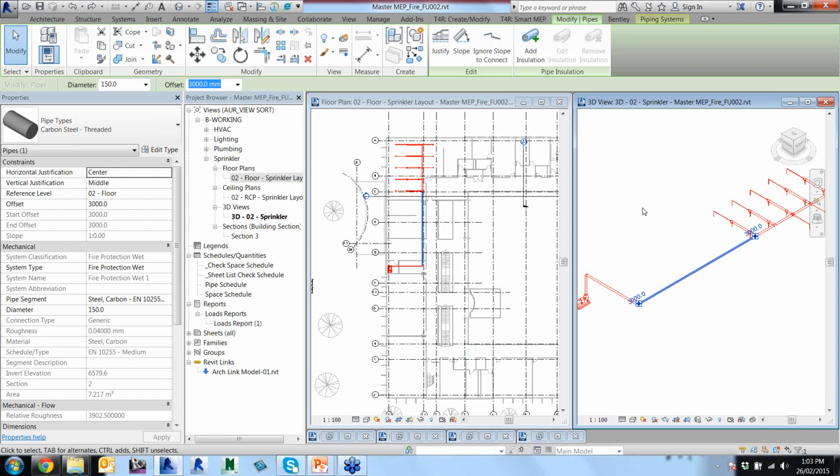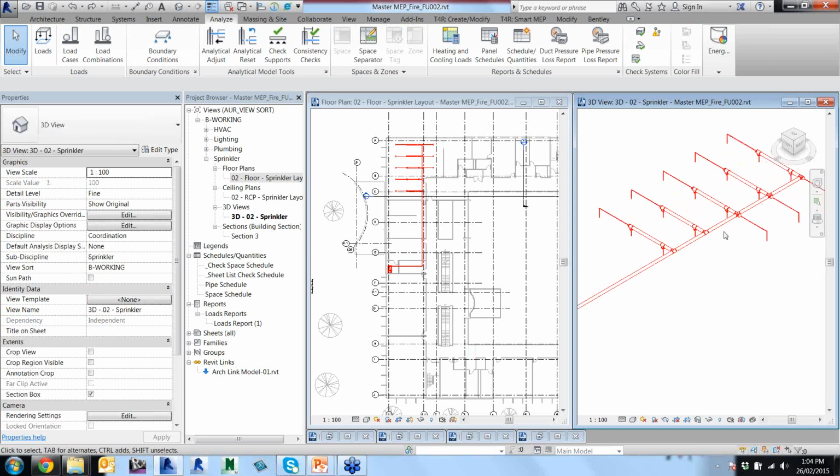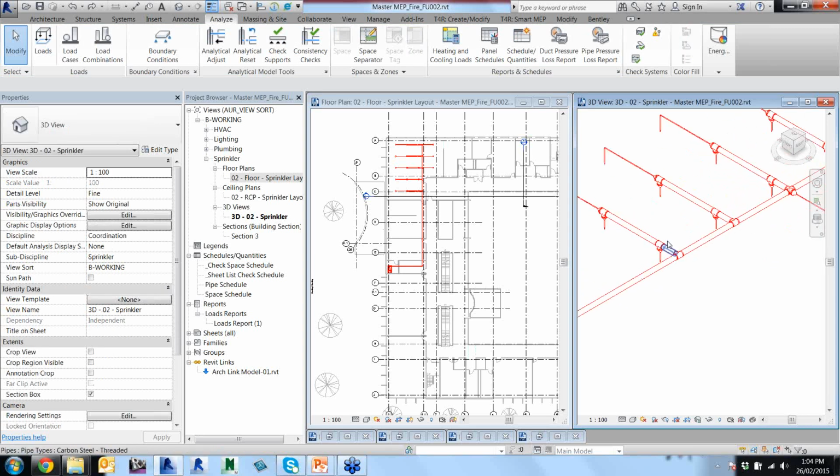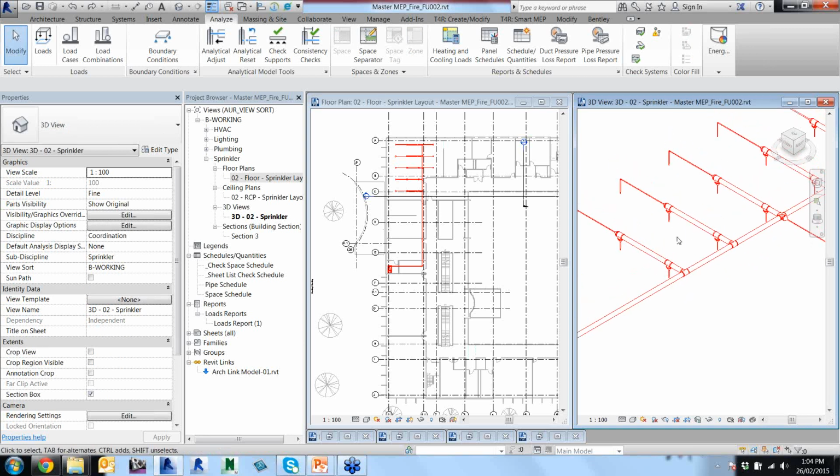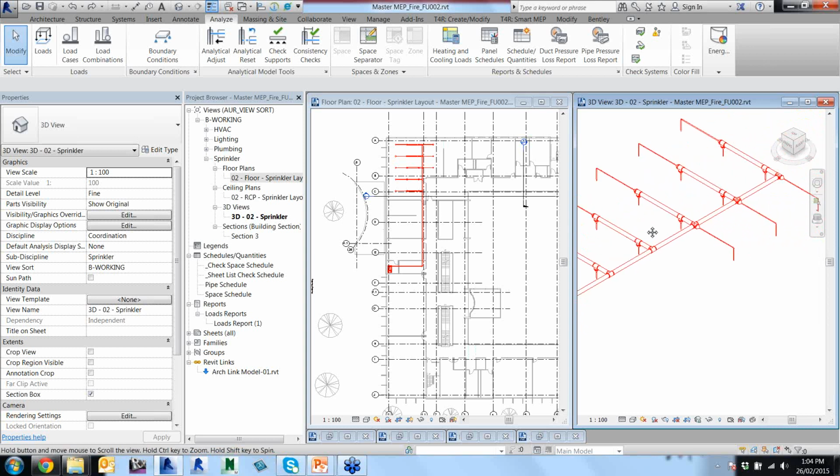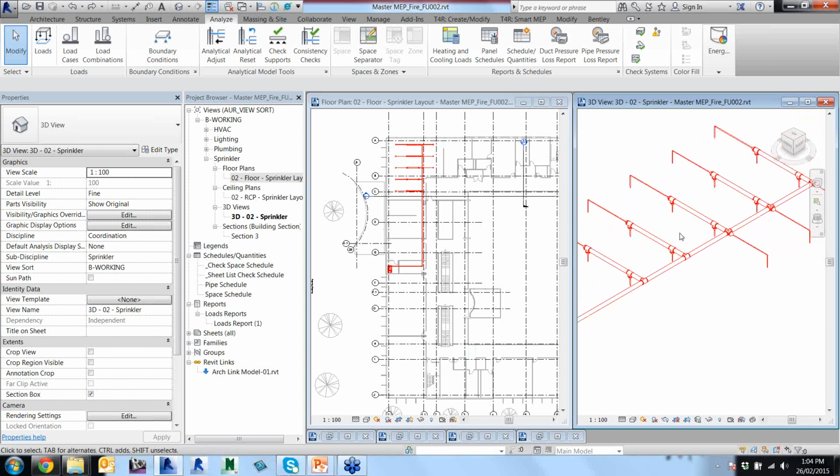So for example, if the system were to try to calculate by liters per second, it would account for every sprinkler head on the system. So it's going to grossly oversize the system, and that's the reason why the auto size tool doesn't work. Having said that, there are some workflows that can help you to effectively size these, a bit of a combination of a manual and a bit of an auto tool as well. And this is something you can do with the out-of-the-box tools that you've got there. So you don't need any kind of add-on or API program to do this.